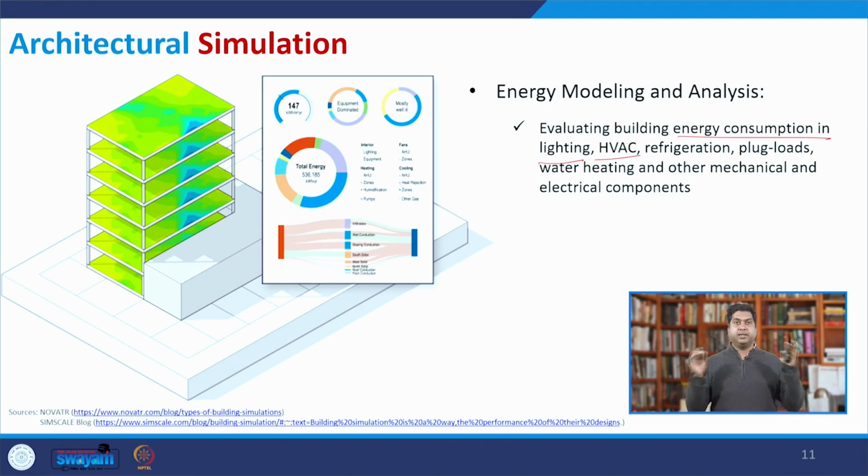If you talk about the overall energy consumption, any building will have two parts. One is the embodied energy, which is linked with the material and the cost of making it, during construction. But normally we just take care of the operational energy, like for artificial lighting, ventilation, then you have some plug load, and certain heating if required, if the building is somewhere in a cold climate, so there might be a centralized heating system.